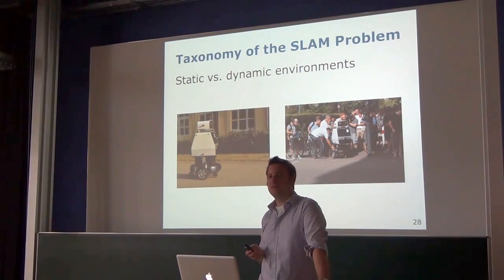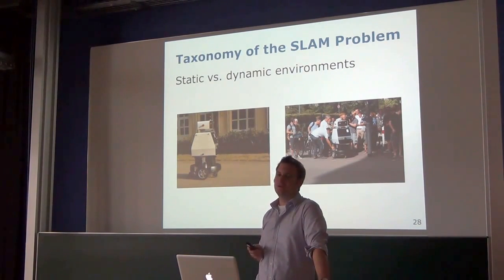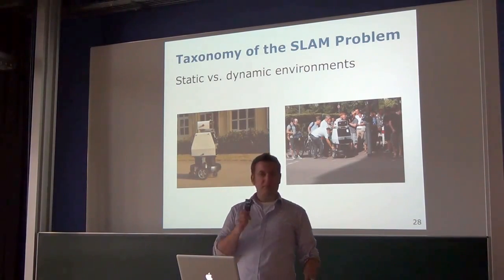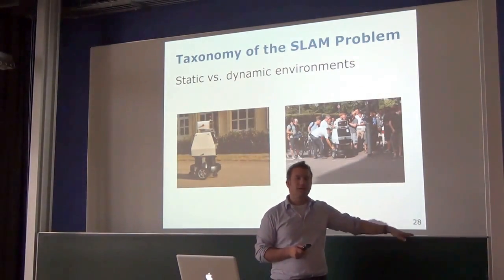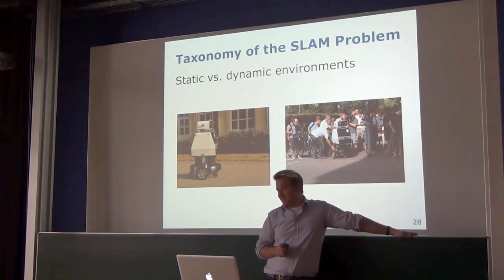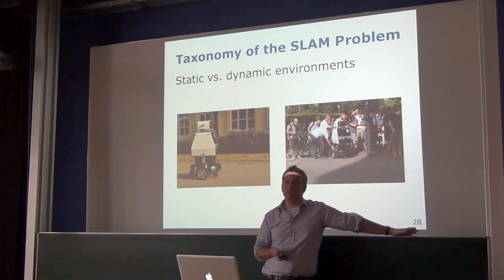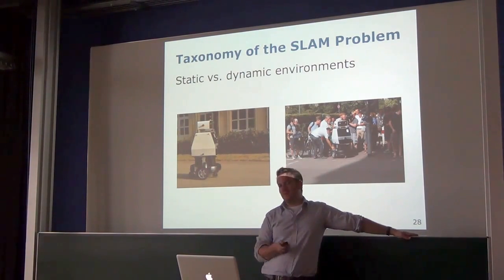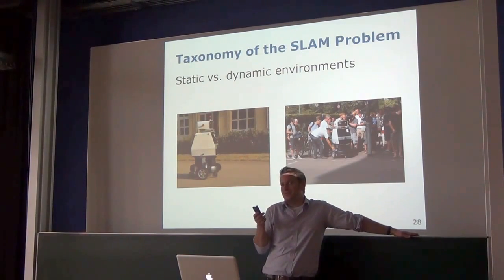You start, for example, somewhere, and you know that position, and you come back to the same position. And so you can recognize you are in the same position, but maybe there are some new obstacles or landmarks added or removed. So if I know that I'm exactly in the same place, of course I can model change, but typically the system doesn't know where it is. When you close the loop. Yeah, but who tells me that I closed the loop? The robot has to distinguish this from its observations.